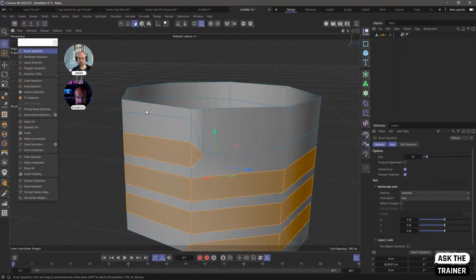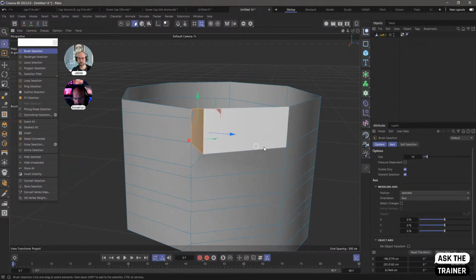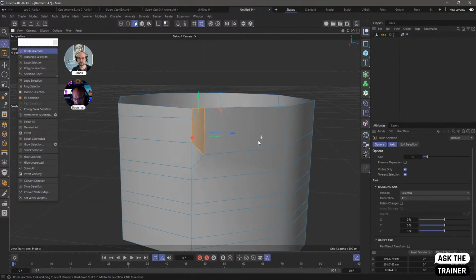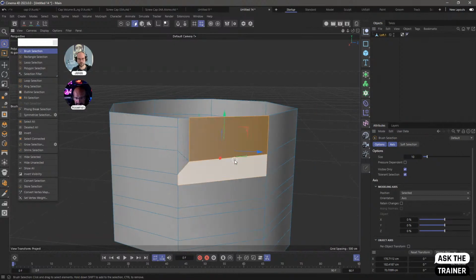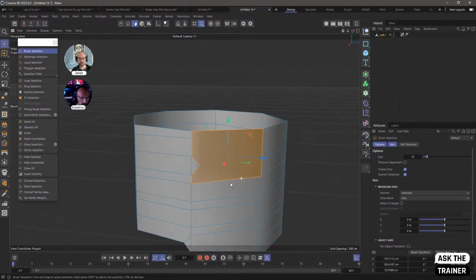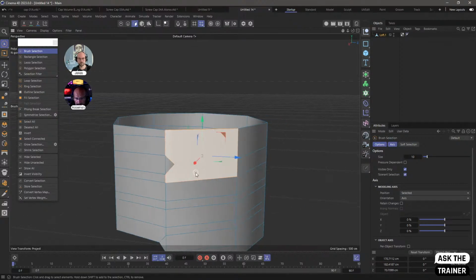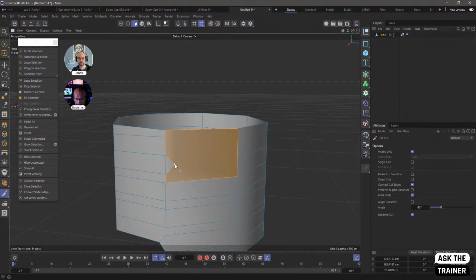Select these and say UZ just to make them n-gons. I don't want this to be a triangle. If you want less visual clutter, you can just use Z things. I'm going to use my knife to cut a line here, escape, then cut a line here, escape. And I have a quad over here.